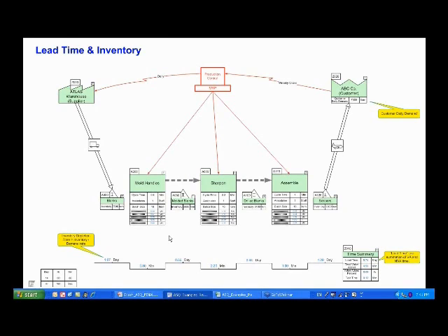Now, inventory is particularly significant, though. It's a key tenet of lean that you want to reduce inventory, because having a large finished goods inventory in particular really can hide a lot of the waste in the system. So, for example, if I have 3 weeks' worth of finished goods scissors just lying out here, I could have a lot of defects happening, but I'm always able to meet customer demand, so I never really have a high severity problem because I'm just supplying that from my finished goods. So I'm hiding the waste that's out there.